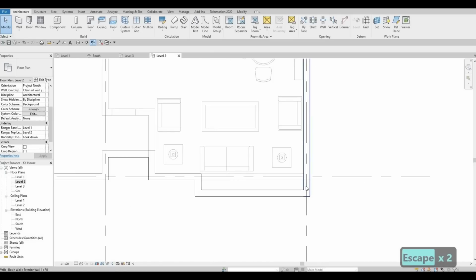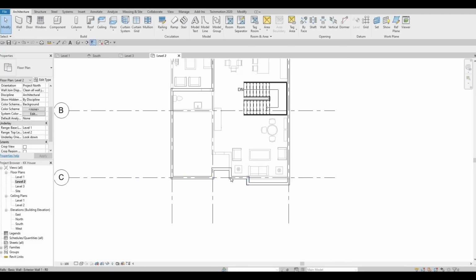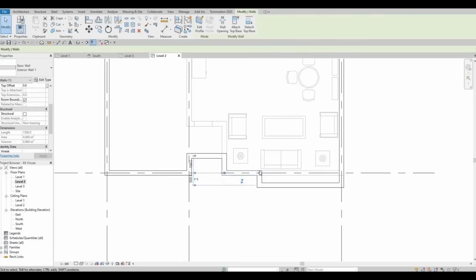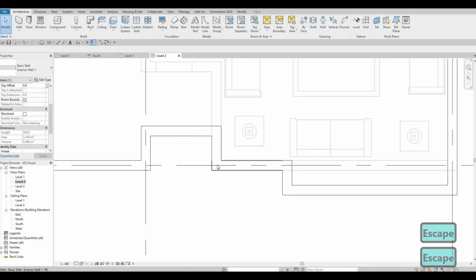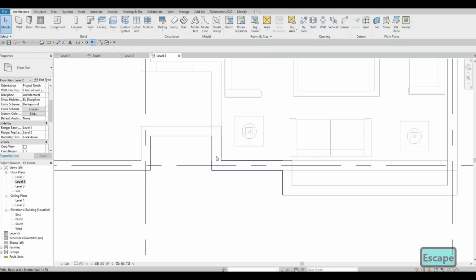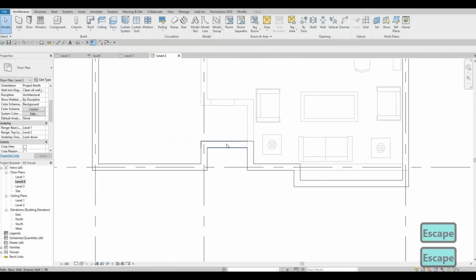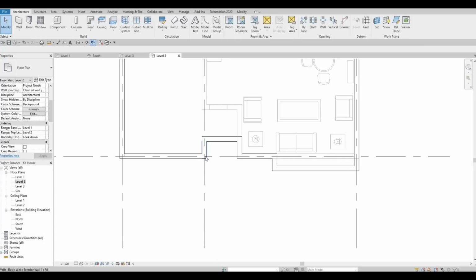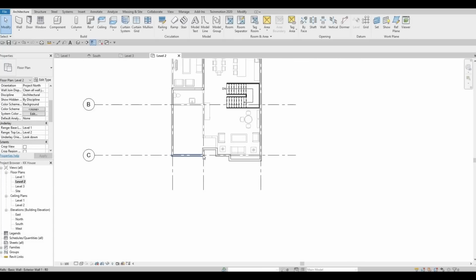So now just a recap. This is 500 and then all the way to 3500, going back to C grid, and this is, I believe, 1500, and then go up 700, so 700, and then just copy it or move it all the way to number 2 grid and go back to the corner here, C2, and then close it off like that.